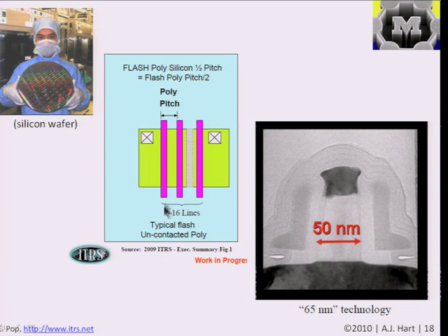And in a general sense, if you think about making a circuit as an arrangement of wires on a substrate, they typically refer to this number as the quote technology of the lithography, as half the pitch between consecutive lines. So if you hear Intel, for example, talk about making a process with 65 nanometer technology, it means that 65 nanometers is half the smallest dimension they can achieve between consecutive lines in their process. And by poly, they mean lines made out of polysilicon.